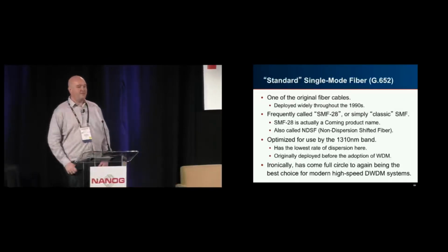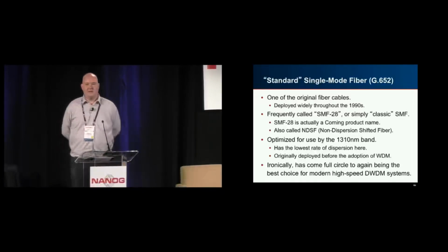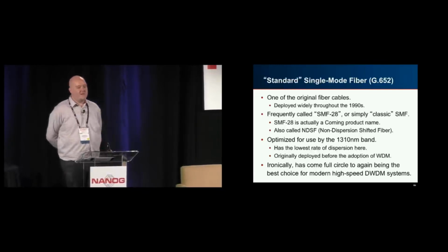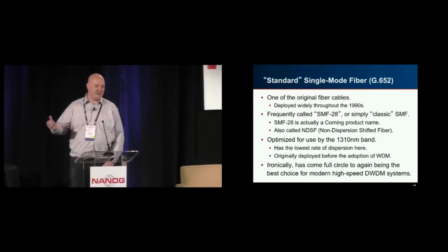So your standard single mode fiber, this is the fiber that was out there in these original fiber cables. If fiber was deployed in the 90s, you can almost guarantee this is what it was. Like I said, sometimes called SMF28. You'll also see it called NDSF, non-dispersion shifted fiber. So just basic fiber. And this was originally designed to be used by the 1310 band, as I said. So this all happened before WDM was ever a thing, right? In fact, this fiber was deployed before amplification was even discovered or available or commercialized.